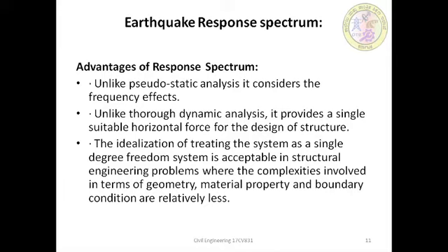Displacement is one response, velocity is another response, and acceleration is also another response of a number of single degree of freedom systems, varying with the natural period, that are forced into motion by the same base variation. The resulting plot can be used to find the response of any structure with a known natural period. So this is all about the response spectrum.